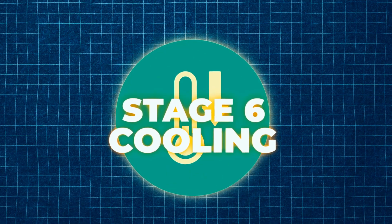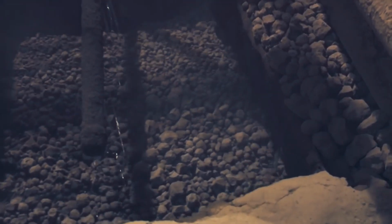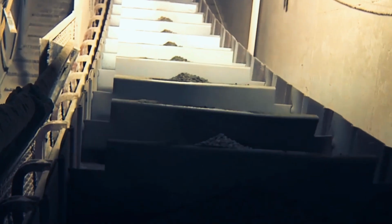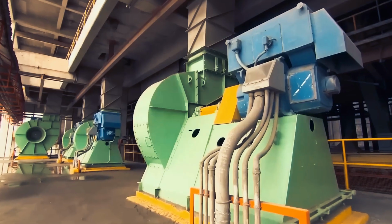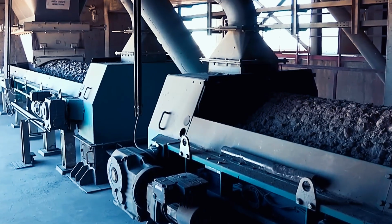Stage 6. Cooling. Using air or water, clinkers are quickly cooled to between 100 and 200 degrees Celsius. Because it changes the texture of the clinker, this process is very important for making sure the quality of the finished cement product. Rapid cooling helps the clinkers harden their mineral makeup, makes them easier to grind, stops them from rehydrating, and keeps them from breaking.